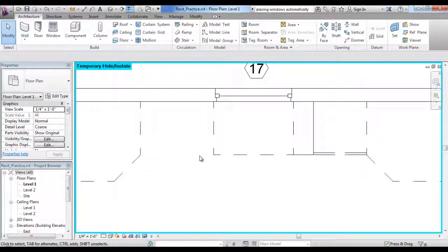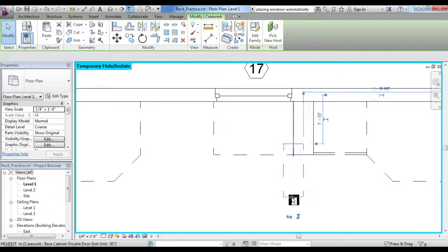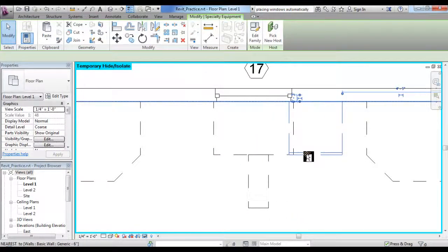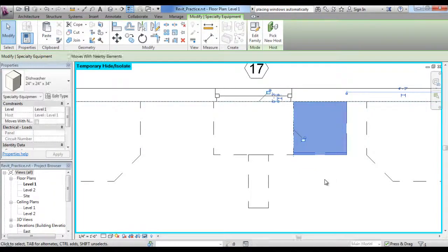but we do need a cabinet here. 2 foot 9 is a standard measurement. We don't need any fillers, which is really nice. Okay. Now remember, this is a lazy Susan. It just rolls around inside there, so you're not going to need to worry about the door opening or anything like that causing an issue. Now, actually, if it's a raised panel cabinet, that could pose a small problem. So really, the better way to do this would probably be to put the dishwasher directly next to this and then move your towel drawers over here.